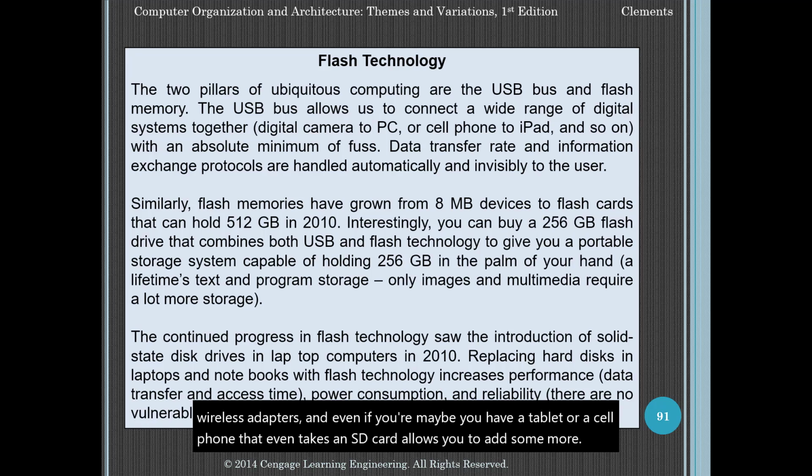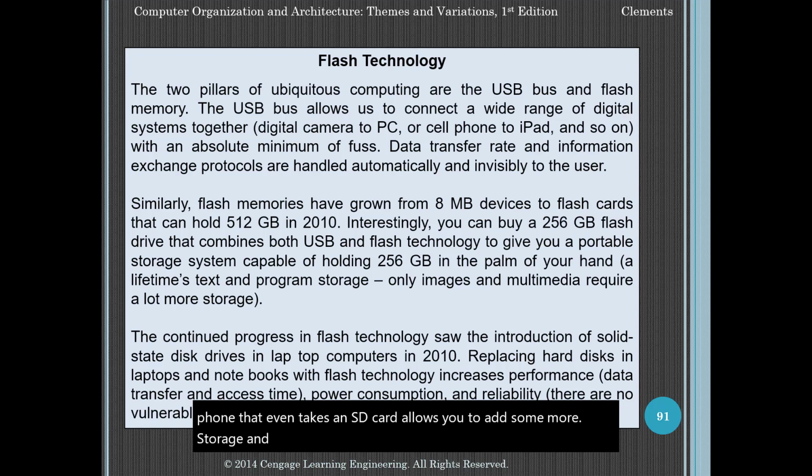And the CompactFlash card interface, it's a host system, uses a 50-pin connector that's similar to a PC card connector, like the cards such as your graphics card that you would put into your motherboard. And these interfaces have an external system. It's not a simple memory interface; it consists of data, address, and control lines. This interface provides a bus, which means the intelligence can actually be built into the cards, for real performance.